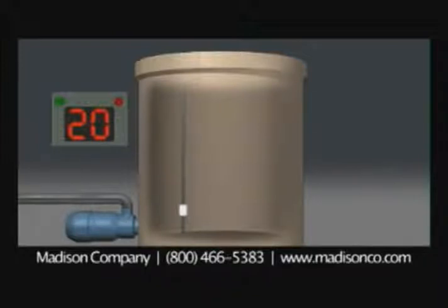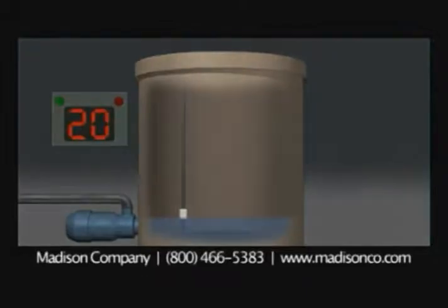A reed switch and resistor network is controlled by magnets in the float to provide a continuous output over a specified range of indication. These sensors provide a precise, uninterrupted output signal and can be designed with either 5 or 10 millimeter resolution. These sensors are custom configurable and can be coupled with Madison Company's full line of digital displays and controllers to meet your application requirements.